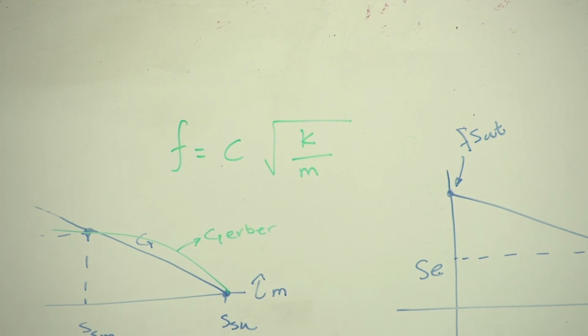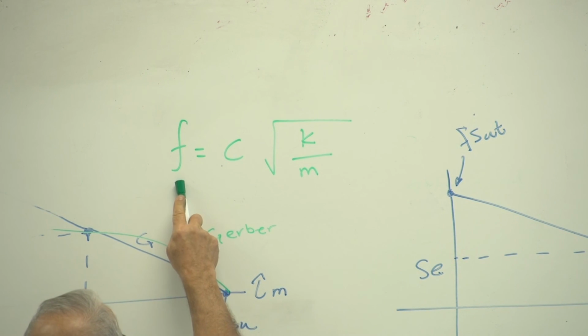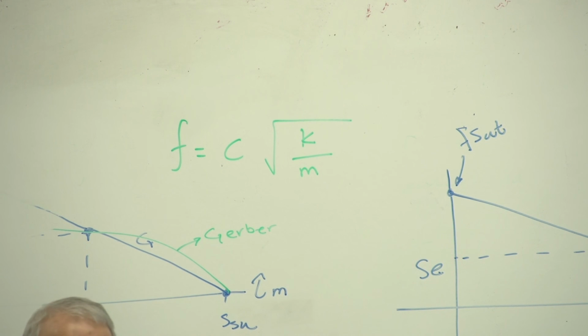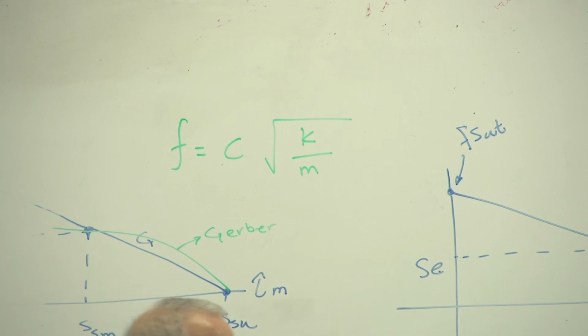Therefore, if I would like this to be high, I've got to reduce that. To reduce the mass, I need to reduce the wire diameter. If I reduce the wire diameter, my stresses are going to go up. Therefore, my factor of safety can't be too high. That's why in springs we generally use relatively small factors of safety. In this case, I'm using a 1.2 for exceeding tau max.